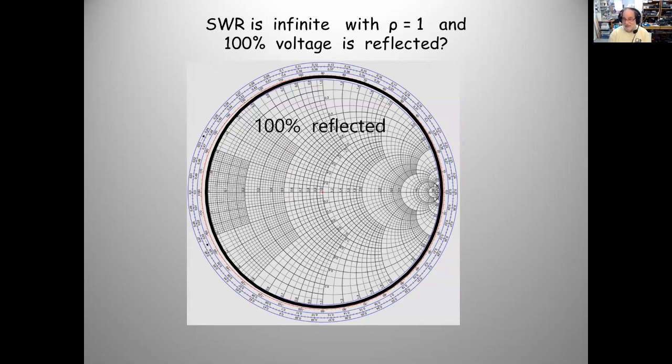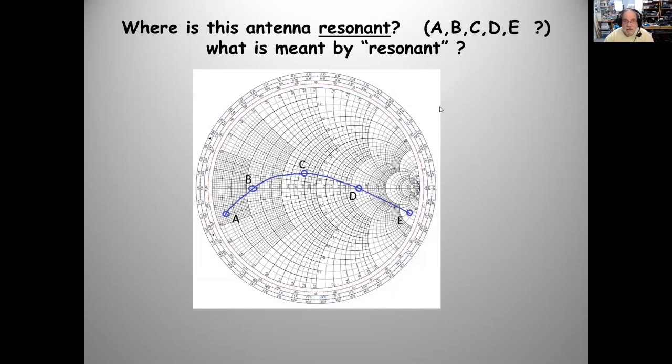This once happened to me, inadvertently. Give me an example of an antenna that doesn't radiate anything. One that's not connected? Yes. So inadvertently, I put my antenna switch, I have a big one over there, and I can always blame it on my grandson who plays over there. So it was on 100 feet of coax with nothing at the end. It was an open. An open isn't a very good antenna. Well, neither is a short. So that's what this would be. You send energy down a cable and pretty close to 100% comes back. Now, granted, the cable has some attenuation. This isn't very good.